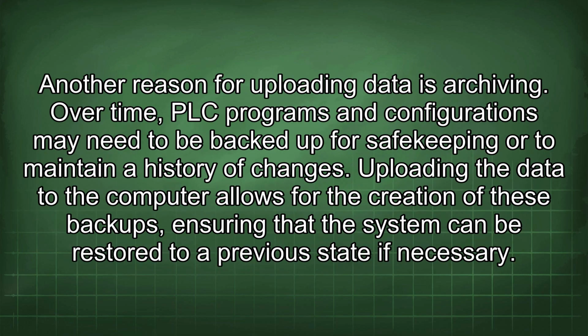Another reason for uploading data is archiving. Over time, PLC programs and configurations may need to be backed up for safekeeping or to maintain a history of changes. Uploading the data to the computer allows for the creation of these backups, ensuring that the system can be restored to a previous state if necessary.